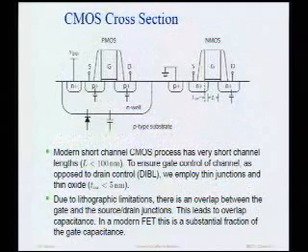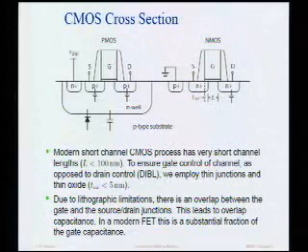Okay, so let's take a brief look at technology. Let's take a cross-section of our devices. Let's start out with our CMOS devices. Now, as you guys have learned in 105 and probably 130 and other courses, the way we build modern CMOS devices is we basically start out with a P-type substrate, and directly in the substrate we can build an NMOS device. An NMOS device is basically 2 N+ junctions and a gate.